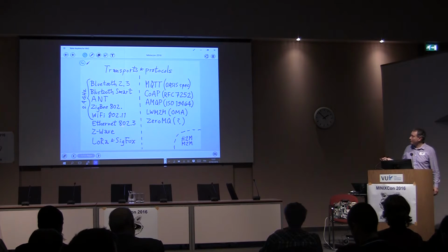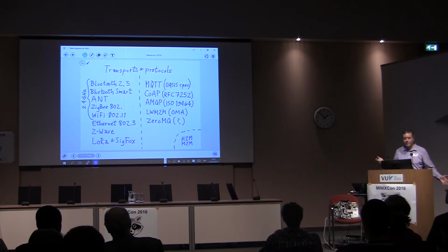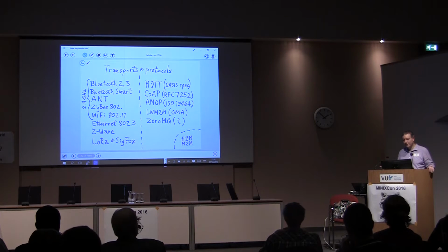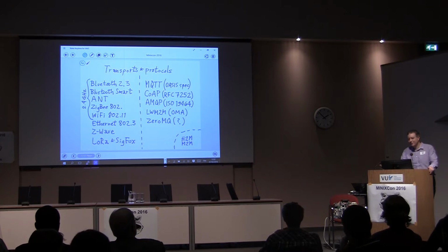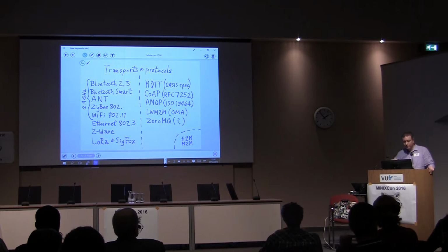And those are the transports on this side, right? You can see that these are different. These are protocols. So these things are riding on those. It's kind of a higher level on the networking stack. And I've left out XMPP, HTTP, SNMP, SIP and so on, the legacy, really heavy-duty protocols, which are good, but they require a lot of battery. So they're not very relevant for IoT embedded systems, not always at least. And they're all just protocols that do similar things. They pass messages to a broker, to a central server, or to one another, P2P.